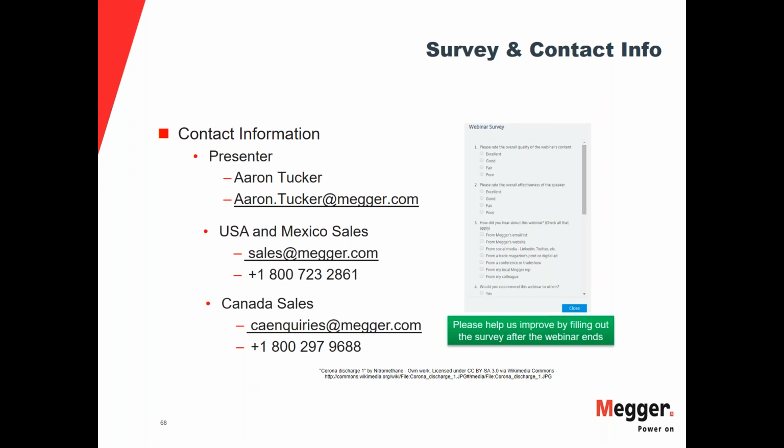So one of the things you may run into is if it doesn't have an actual nameplate that has maybe a vector group or even the configuration in there, and so you have a couple of problems here. One of them is if you just guess and say, oh, well, it looks like a DYM1, or it looks like X, Y, or Z, whichever configuration you pick, you don't know the full characteristics of it without the drawings, without the actual nameplate. You could run into issues where you think you know exactly what it is, but when you test it, it fails, but it didn't fail because it's actually bad. It's because your connections were incorrect.